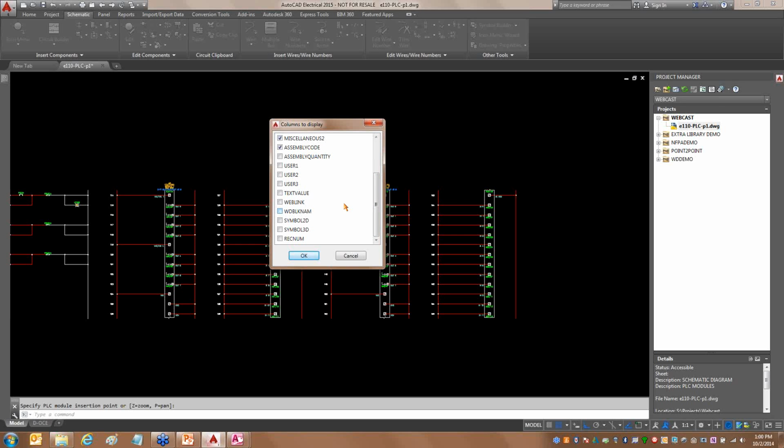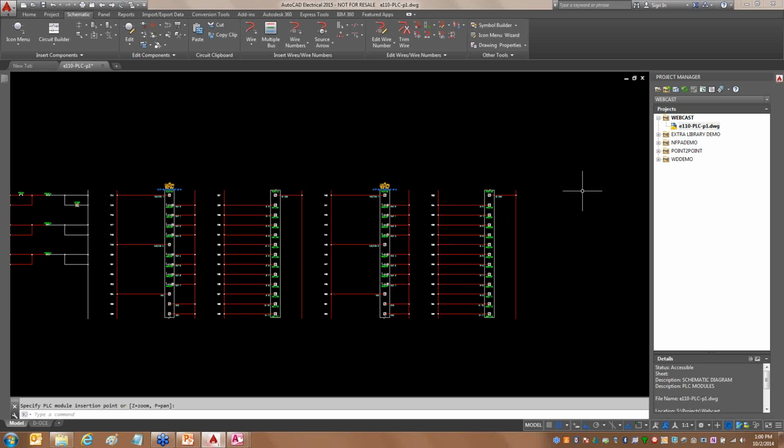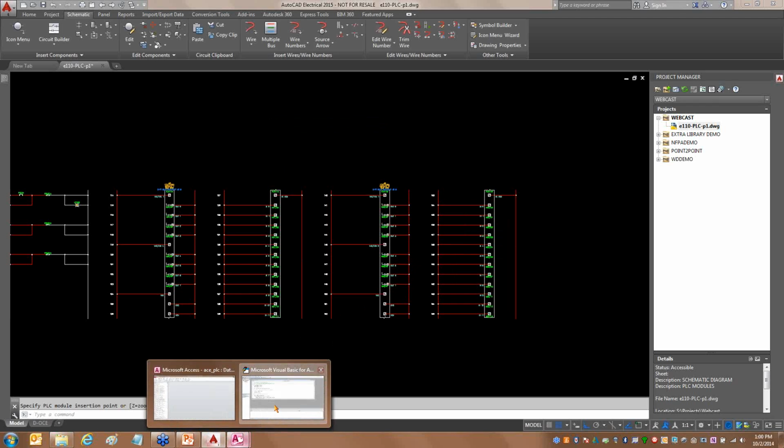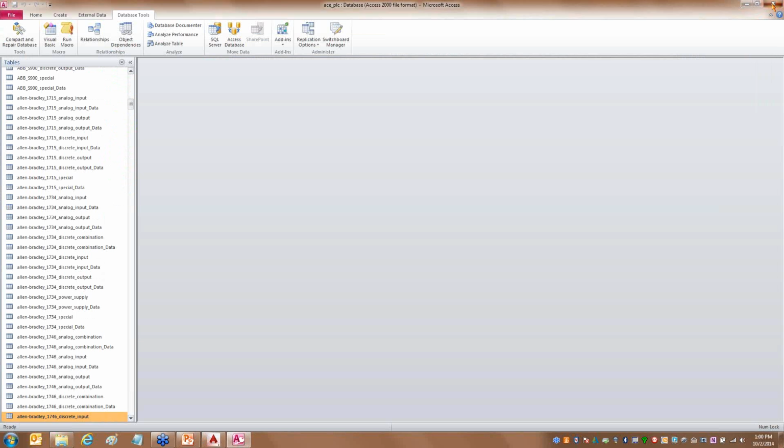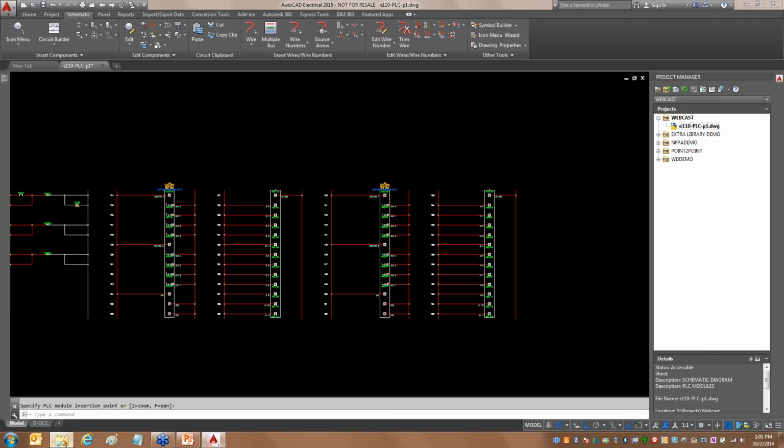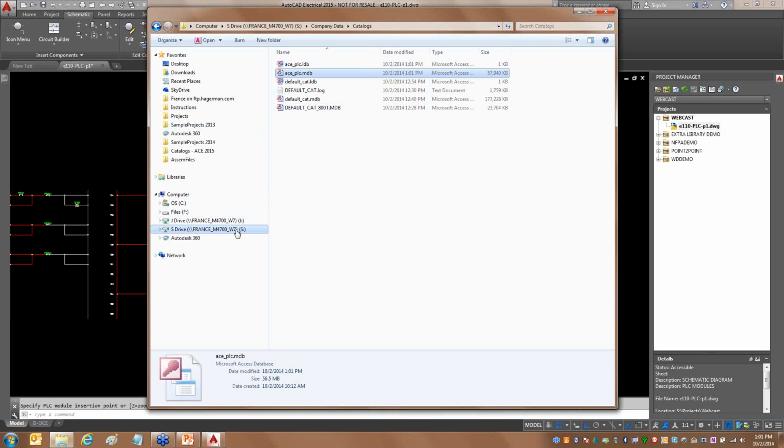And on the question of pin lists too, Todd Hall had a question regarding pin lists that end up longer than 255 characters. Now the documentation says that the limit on the pin list field is 256. He mentioned that they removed the pin list continue column, and I've been using electrical for a long time, but I didn't pay too much attention to the pin list table until the last few years, and I don't recall ever seeing that column. Are you aware of a time in the past where there was an extra column in a pin list table that would let you extend the pin list beyond 256 characters?